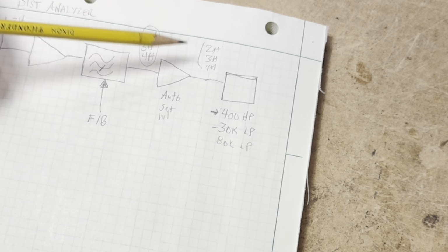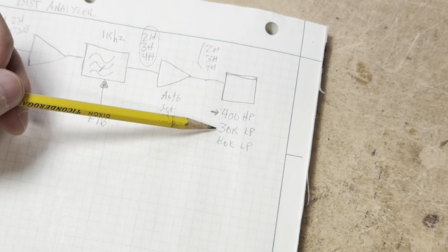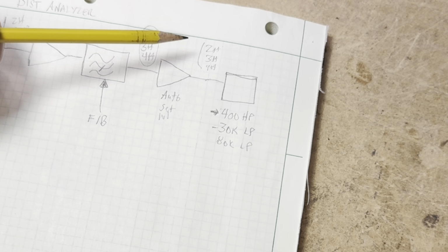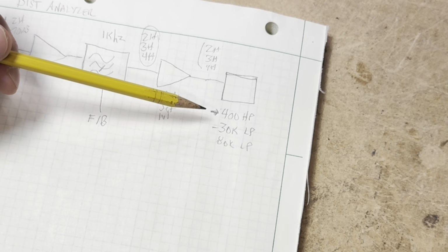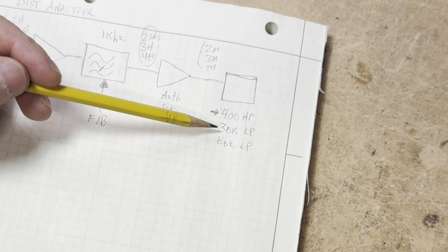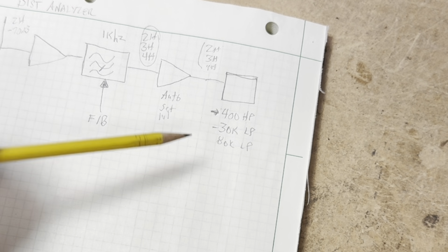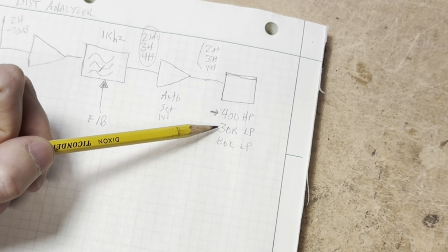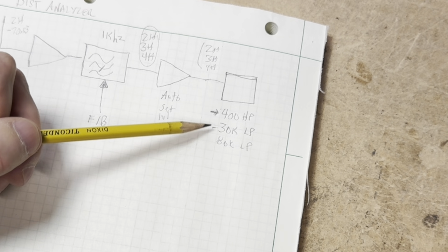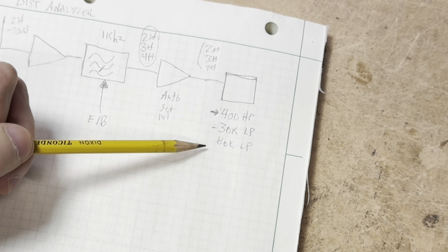Let's say we're making a measurement at 15 kilohertz, our second harmonic is 30 kilohertz. Well, if we're attenuating our second harmonic at 30 kilohertz, then we're going to get a better response on distortion measurement because we're attenuating components that we need to otherwise quantify. So always take into consideration when you're using any kind of output filtering how that might adversely affect the accuracy of your measurement.